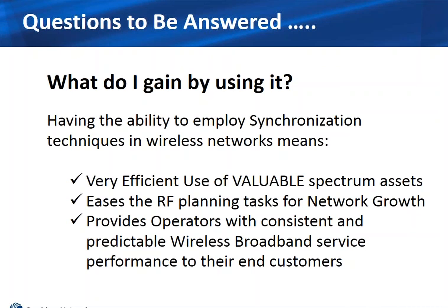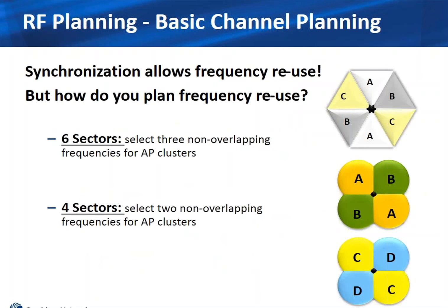All right, next slide. So we talked a little bit about that frequency reuse. This is just giving you a little bit of a visual of how synchronization allows that frequency reuse. If we imagine that each one of these little cells or sectors, by letter designation, is a separate frequency. So on the very top one I have frequency A, frequency B, frequency C. With synchronization I can use that exact same pattern on the backside of that same tower structure. Frequency A, frequency B, frequency C. If you didn't have synchronization, this would fall flat.